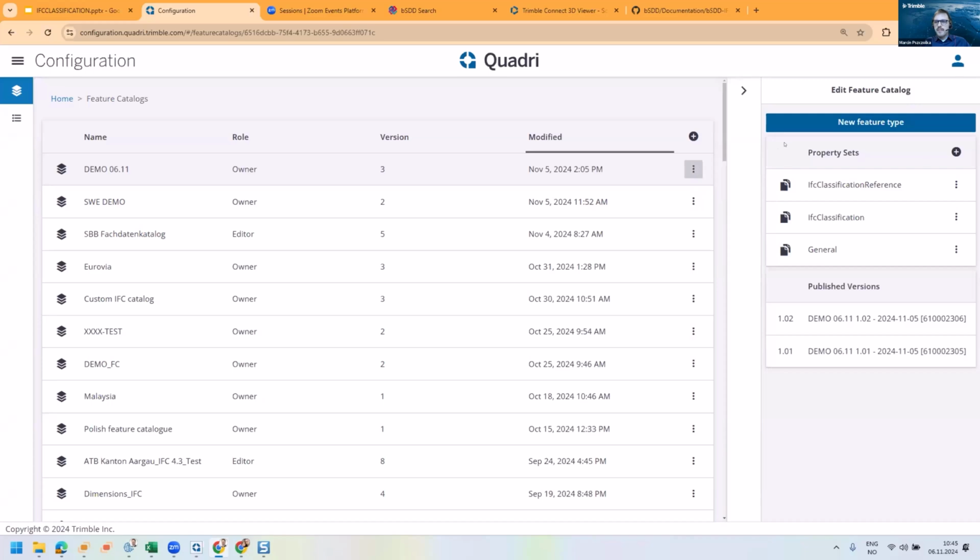This is my catalog, and also to this catalog I attach property sets. Why do I attach property sets? Because I would like to, in the next steps, connect some data to these property sets. But what is nice about that is you don't have to punch all the values manually. You can export this catalog to Excel. And for example, this data you can attach using a spreadsheet.